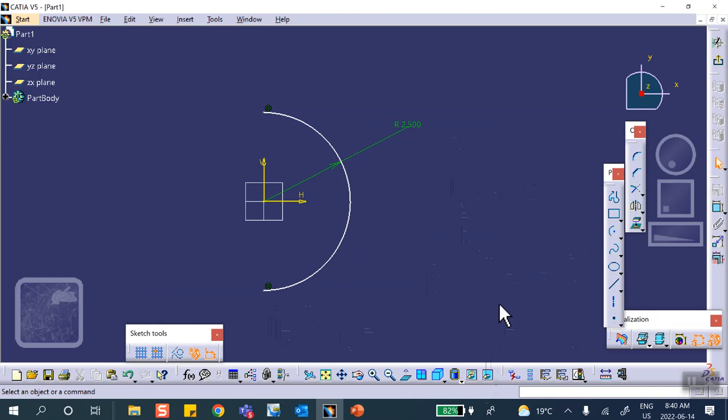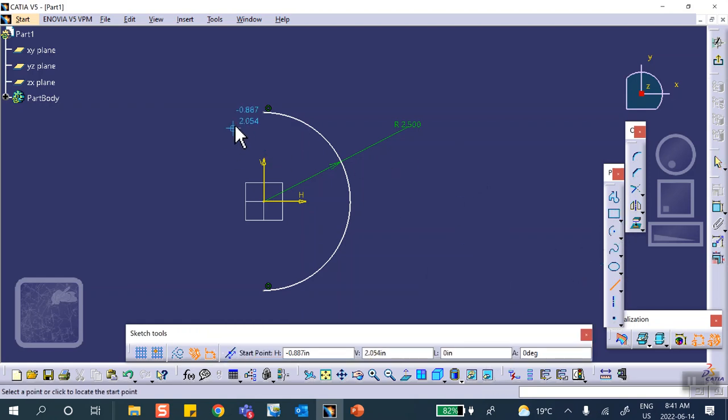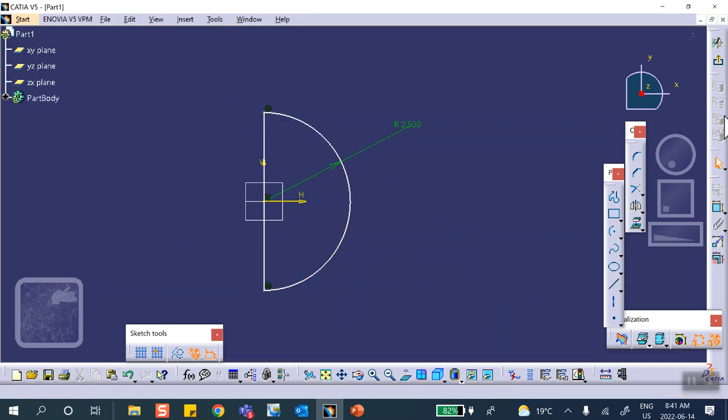An open profile can be padded by giving it a thickness. So basically it becomes a sheet metal type thing with a given thickness. If it's open, you can pad it, but not as a regular pad. But I'll close it. That's not what I have. All right, exit.